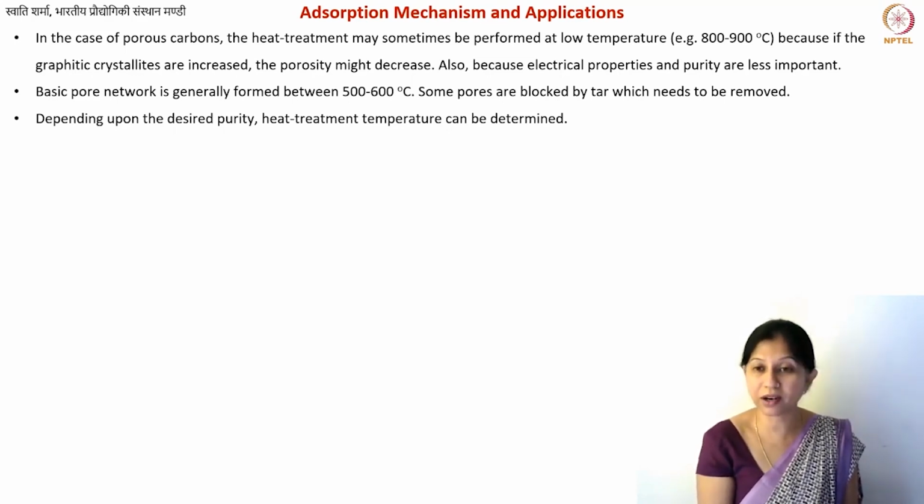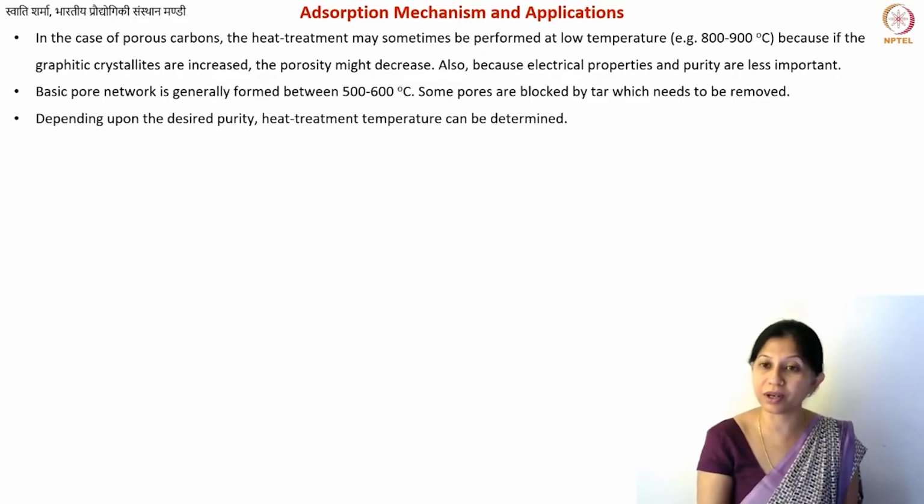But if you're making a filtration column where a reasonable purity, let's say 96%, is all right for you, in that case you don't care whether you have short range order or not, what the La-Lc value is, or what the electrical conductivity is. You rather care about the good porous network. So depending upon that, you will determine your heat treatment temperature.